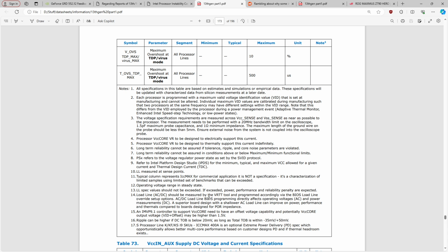So this sounds like if you set the AC load line really, really low, the CPU runs on less voltage. And apparently we're going to trust the motherboard vendors to measure what the optimal AC load line is themselves using a test tool, not real CPUs, and then we're just going to pray that it actually works in practice, I guess. This statement to me is basically asking for things to not work if you're Intel.